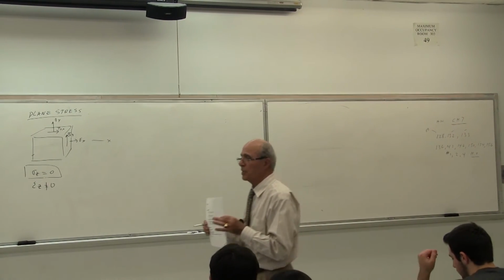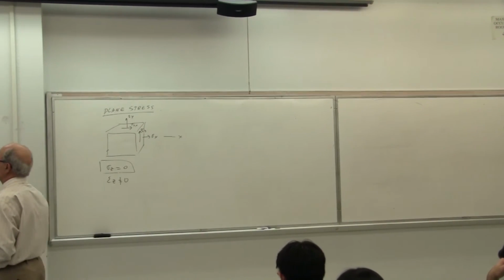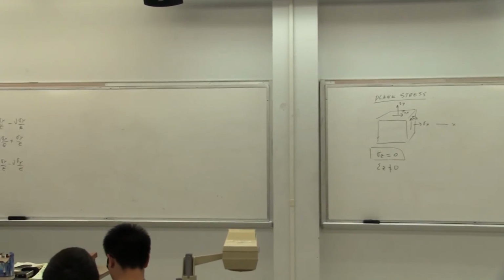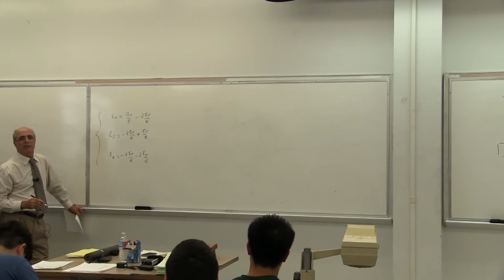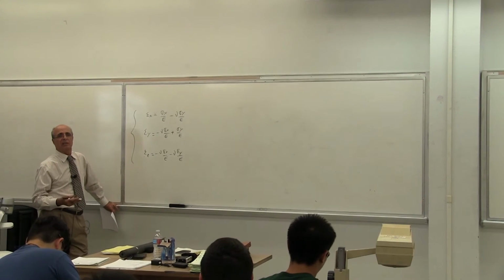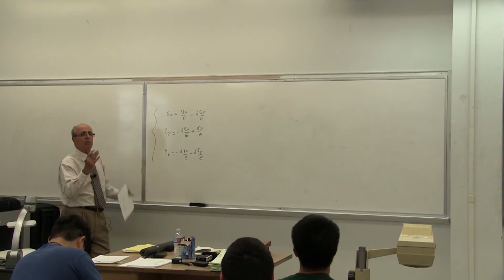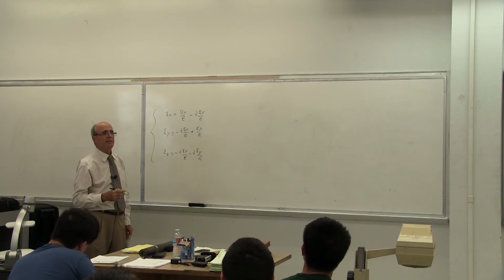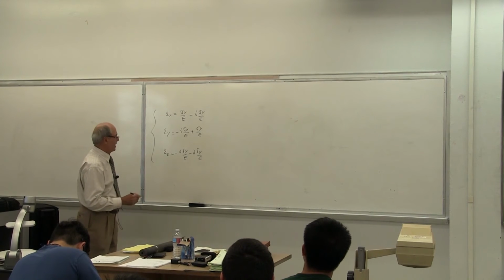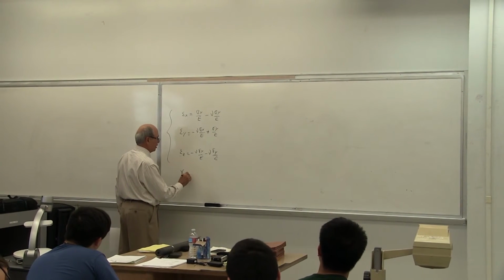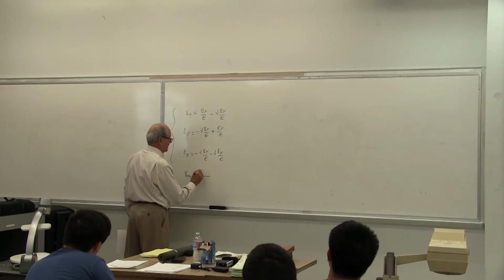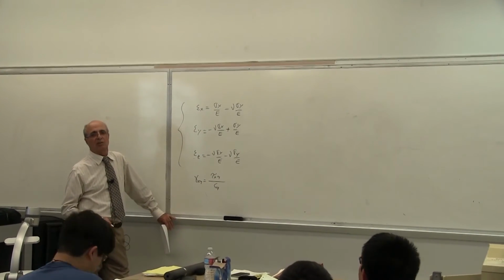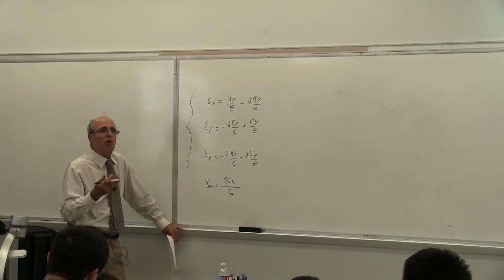And find which one is the largest. Remember how you were calculating the tau? See, that's what some people actually didn't do. When you were calculating sigma versus tau, you come up with this circle, and you draw two more circles. Is that correct? That is the absolute maximum. Find the radius of the larger circle. Here is the same thing, because we have in plane and out of plane, so that's the question I'm asking you to do. Absolute maximum shear strain means you have to go out of plane as well and check to see which one is the largest. That we have done. When I do it, you remember it.